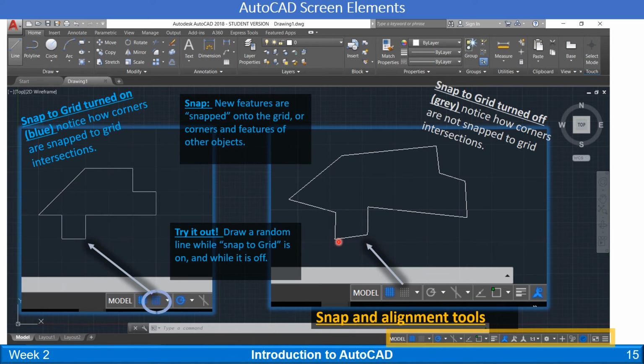So if it's off, you can see the line is not constrained to be anywhere. It's not lined up with anything. It's not stuck to any corners. Sometimes you want to put something in a random position, and you have to turn off your snap in order to have the freedom to move things to any position you want. But if you want it lined up, you just turn your snap on, and you can have everything nice and lined up with one another.